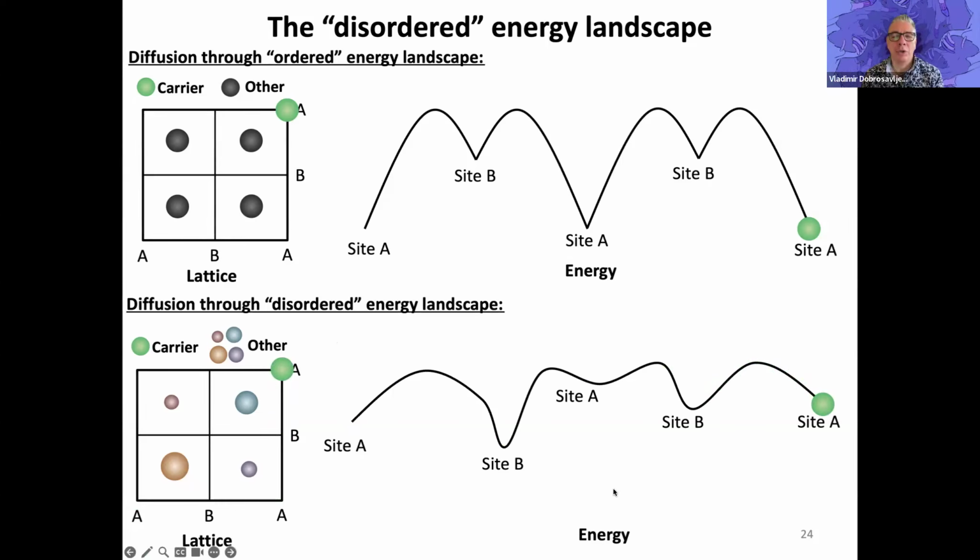Did you try to calculate the distribution for barriers? If you look at local sites in the crystal, then each site in an alloy will have a different barrier, say, but you can do a histogram and you can try to characterize the distribution functions. So yeah, exactly. You're absolutely right. We actually can also do cluster expansion on that. I didn't cover it in these slides, but we are doing that. So we can fit the diffusion barrier as a function of local environment. So this is sort of like what you said, we can fit the histogram in a reasonably accurate way.